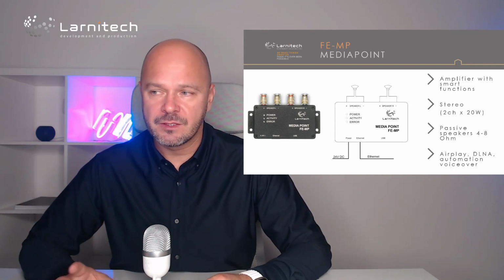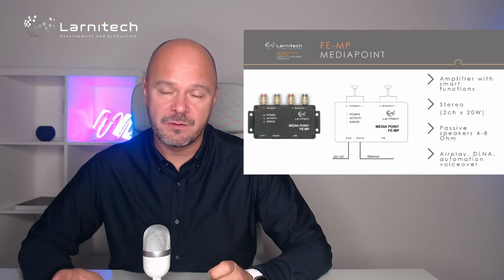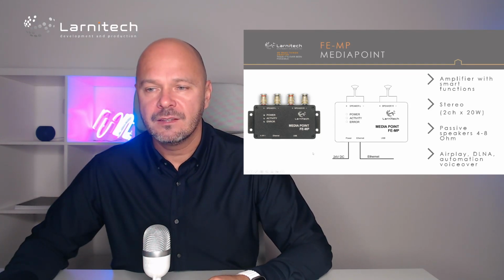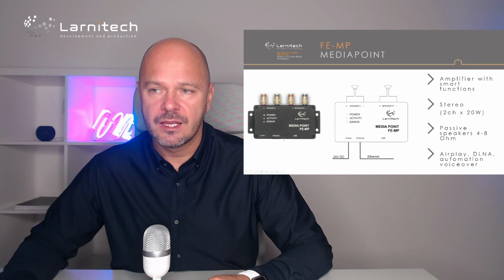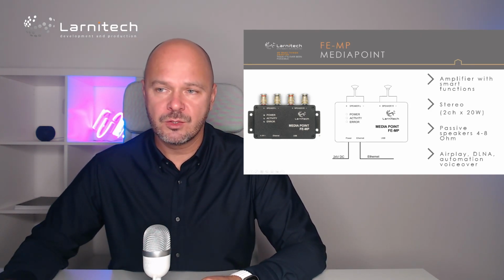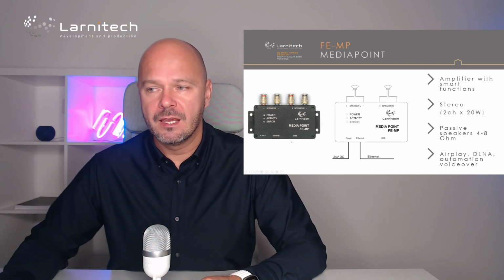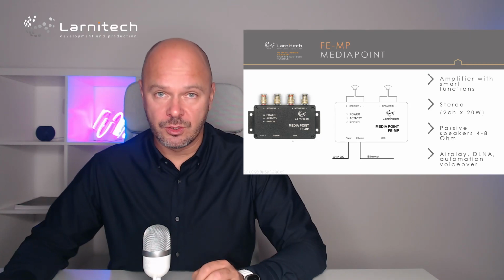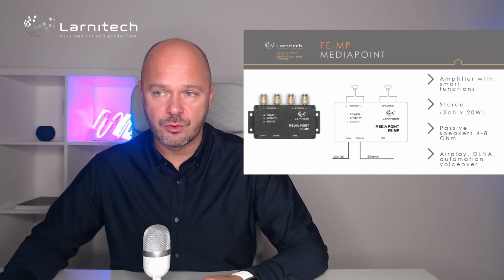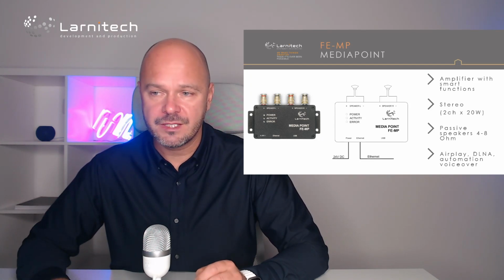So you will need something like maybe 3 amps, maybe even 4 amps of 24 volts. Then it has an Ethernet connection, and it has a USB connection. So why do we use USB? We can connect a Bluetooth dongle to USB, and then it will also be available through Bluetooth. So this is why we use it.